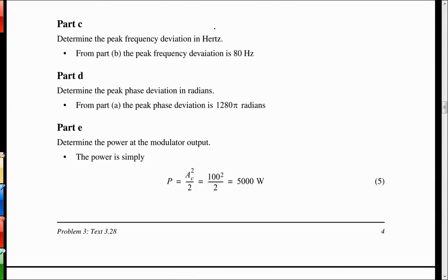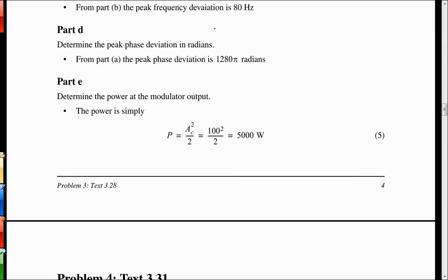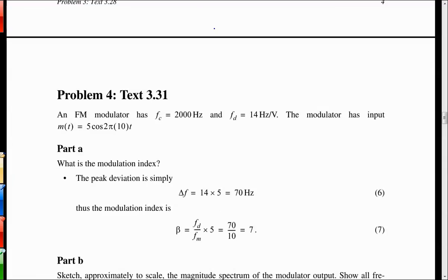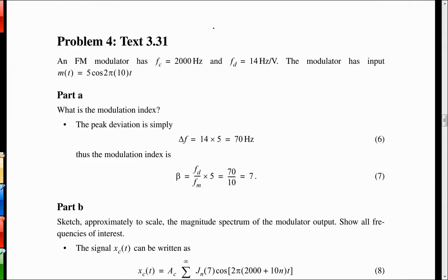The power in the signal, regardless of what's going on inside the phase or the frequency, is still just A squared over 2. I'll probably ask you that question because I'm looking for you to be confusing this between AM and PM or FM. This is constant. It never changes. It doesn't matter what the message is doing. Unless it's an extreme modulation, which I said was impractical, one that would be so wide that it would cross down through DC.